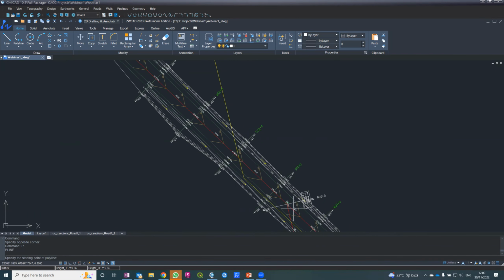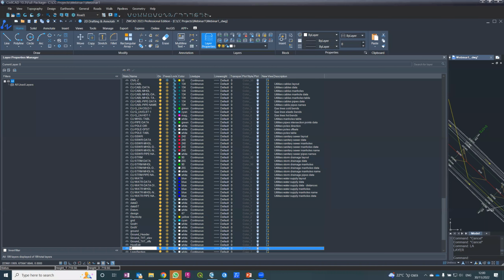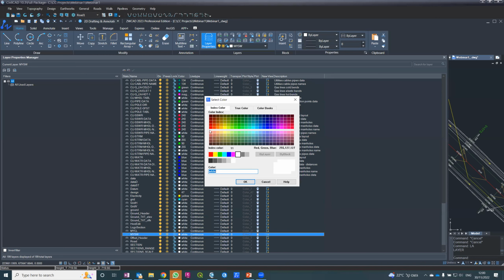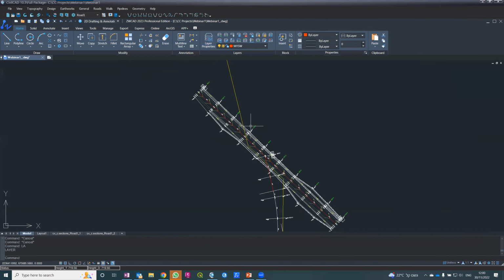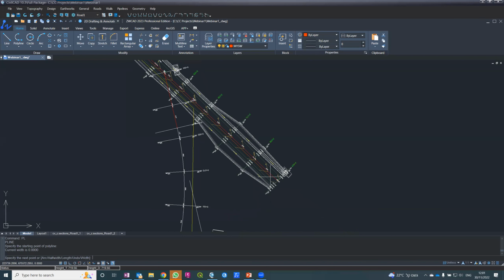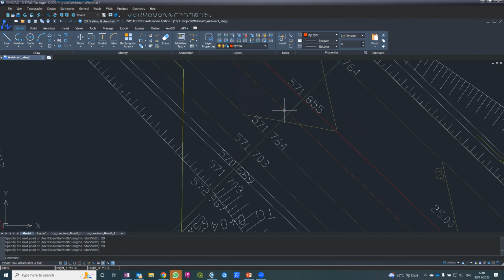So let me start. I'm opening a new layer and I will call it my sewage. And my sewage will become the current, and I will give it some kind of a color, reddish color like this. And it will start somewhere here, under the asphalt, each 20 meters. So I'm just creating a polyline with vertex each 20 meters for my pipeline, this one.